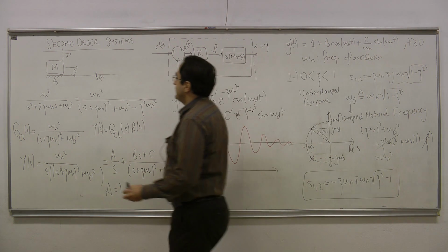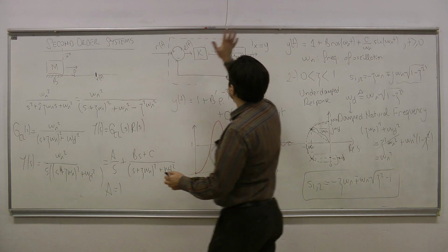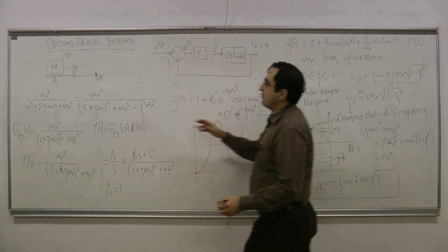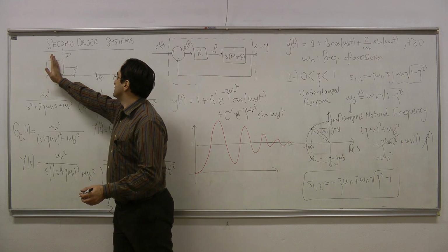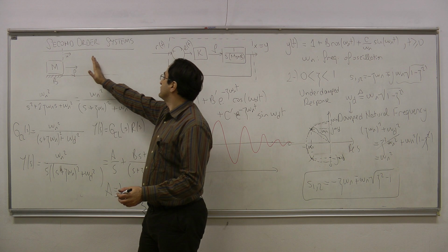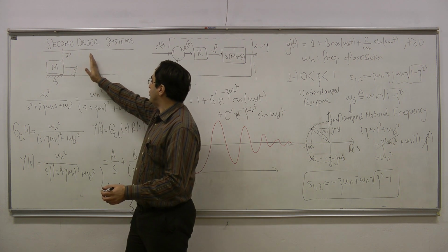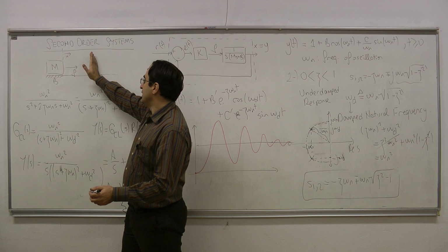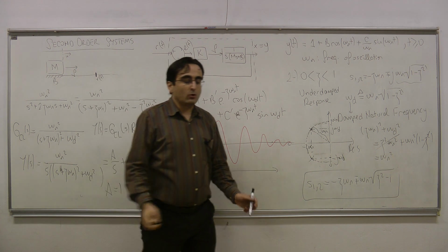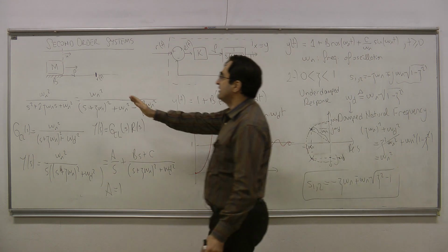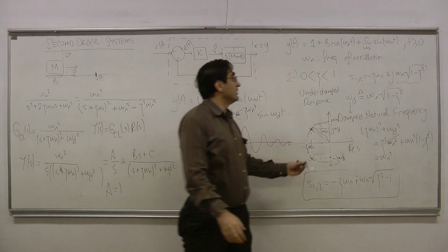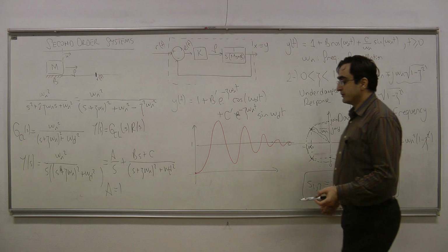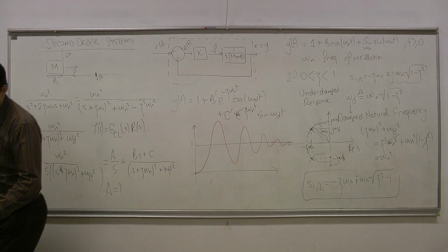Okay? So here, what does that mean for our control system? This control system then would be able to achieve its aim as time goes to infinity. Okay? What would happen to this mass? It would start in the direction of the desired point, and then it will pass it, but it would come back and it would oscillate around the desired point, and it would converge to the desired point at the end. Okay? And the oscillations would actually decay, but the oscillations do not really disappear. They are still there, but they are decaying. That is why we are calling this case the underdamped case. Okay? There are still oscillations. They do not disappear completely.